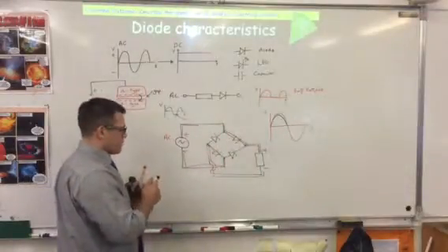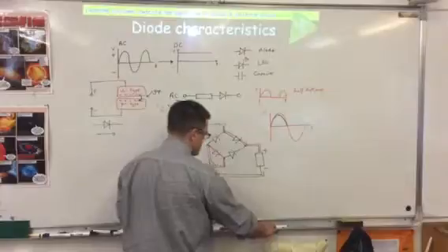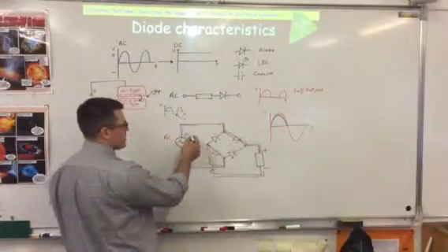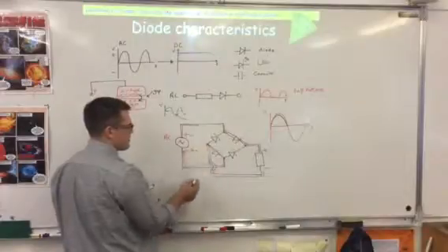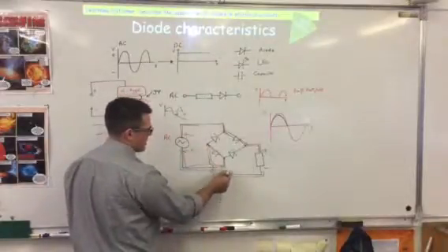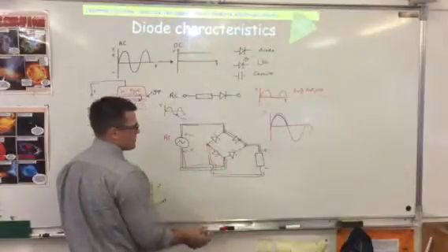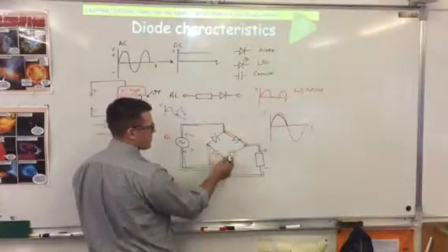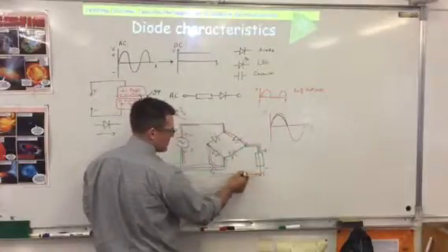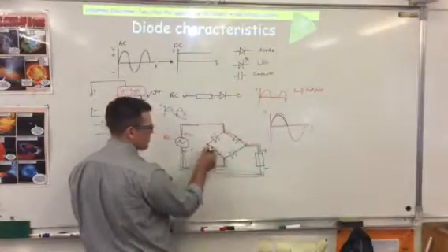Now, the way that the rectifier circuit works is that when we do the negative half of this cycle, so I now make this negative and this positive, the current now will go this direction around the circuit and will come in at this point, okay? It can't go back through there, so it will go through this diode, through the resistor, round, and come back to this point.